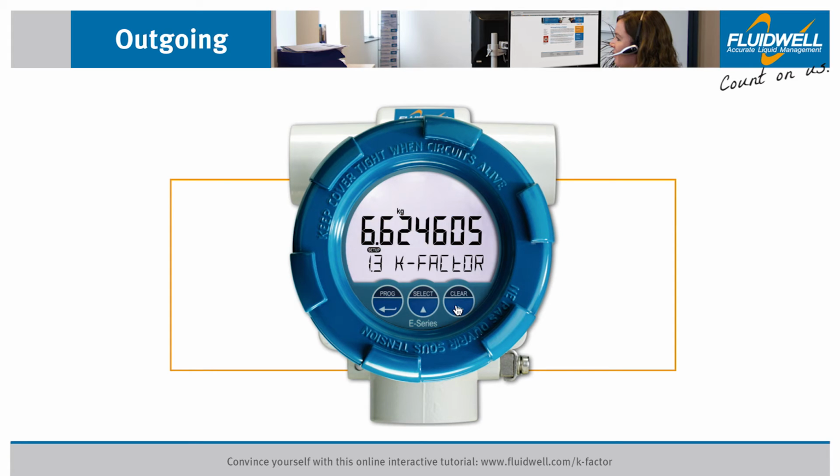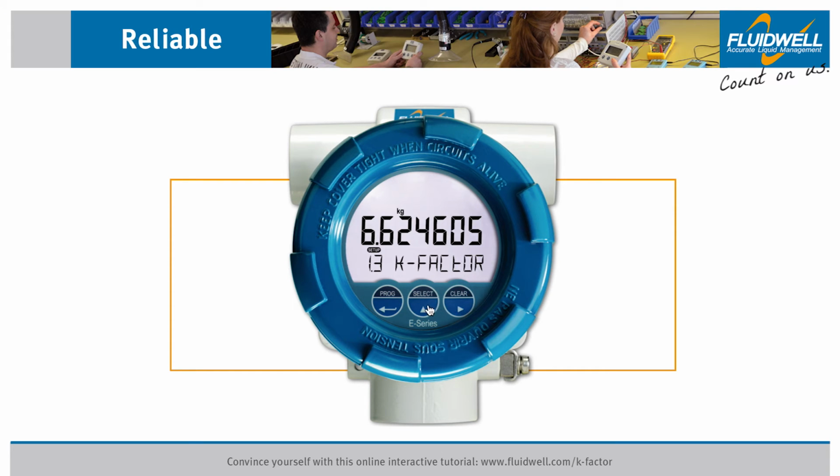In this tutorial, we want to add a multiplication factor because the 7 shown digits are not sufficient for our application. Go to Menu 1.5 Multiplication Factor. Press Prog to change this setting. In this example, we want to add a multiplication factor of 10, so we select the 10 value. Press Prog to store this setting. Next, we are going to configure the flow rate and K-factor in US gallons.